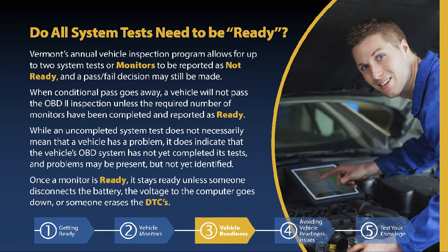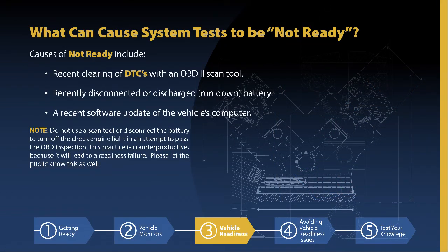Once a monitor is ready, it stays ready, unless someone disconnects the battery, the voltage to the computer goes down, or someone erases the DTCs. A system monitor may come back as not ready if the DTCs were recently cleared, so be sure not to clear the codes prior to checking for readiness. The system monitor may also be not ready if the battery has been recently disconnected or discharged. Software updates may also reset the computer systems, resulting in the systems being not ready.